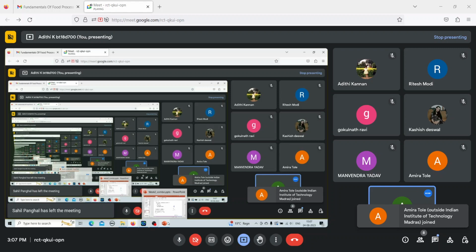Okay, in order to describe viscoelasticity, we learned the different kinds of tests for viscoelastic behaviors. Apart from this, if we want to model a fluid flow somewhere, we need to develop a model for that kind of fluid. So different kinds of models were developed to describe different kinds of viscoelastic fluids, and those are the models that we'll be discussing right now. In each of these models, you will have a spring and you will have a dashpot.